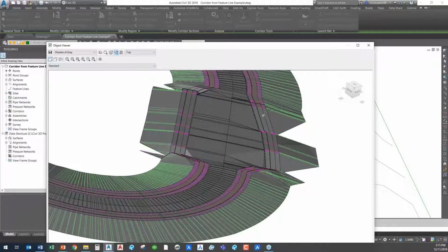But you see what also happened in here. You see how it also dropped the elevations at those points, where I said at this corner and at this corner, drop the elevation instead of shooting it down to the existing ground. So it dramatically, see the slope down here, the two points that I put on each side, it dropped it to the elevation. So it's following the feature lines and stretching my roadway not just horizontally to get my lane widths, it's also stretching it down vertically to match up with the elevations on these outer feature lines, which is really, really nice.